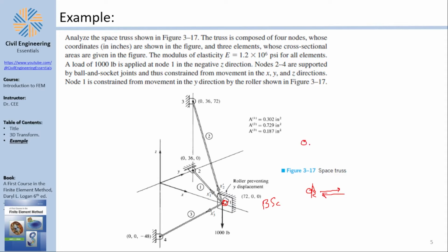Even if you have this type of roller, you have studied this in statics, if you apply, for example, a force going up, then you assume that the two reactions are going to go down. Your assumption here is that the roller doesn't get detached. And this basically means that our drawing for the roller was actually a lie.